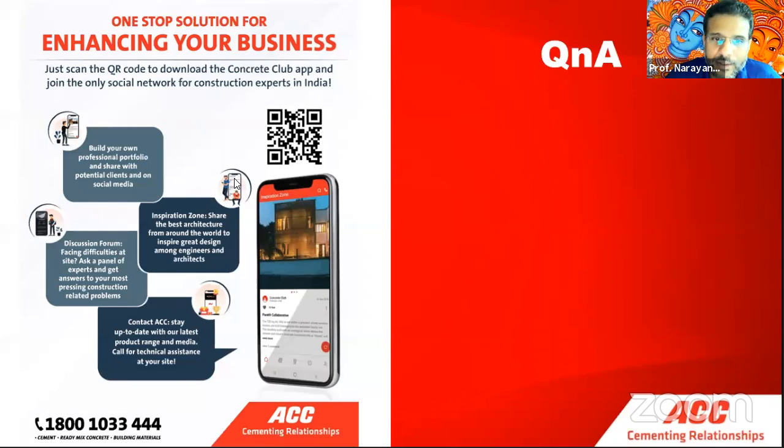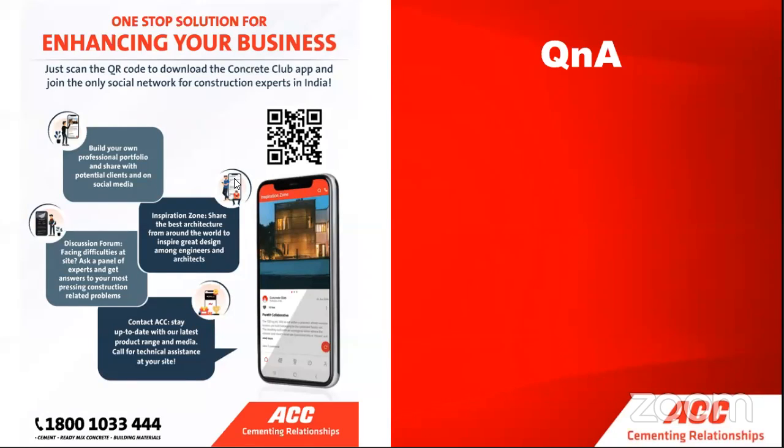Can you explain whether self-compatibility is also assessed with the optimized aggregate? Yeah, optimized aggregate volumes can give you the optimized paste content. But again, it is subject to you doing experiments because every model or most models assume spherical aggregates, and you don't have spherical aggregates, right? So you probably will have to test them out and validate it.